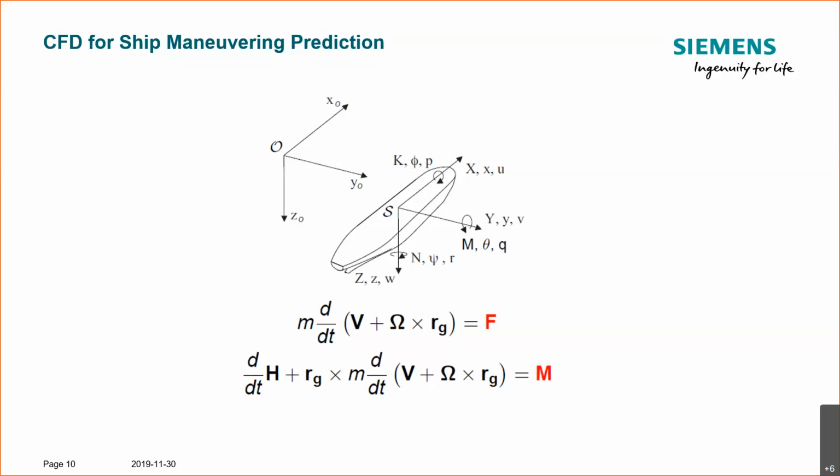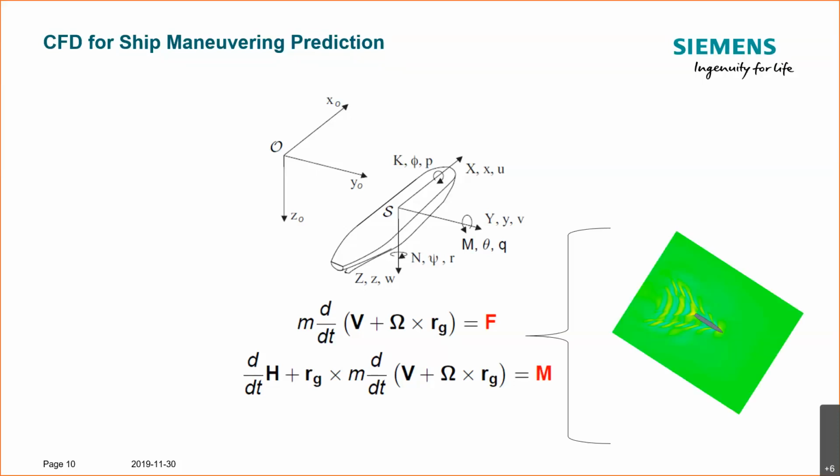So let's make our lives easy and just resort to Navier-Stokes. So basically, we will build a CFD model of the ship in a finite domain and specify rudder and propeller action, and then we'll get the motion responses and all the other sought after metrics from CFD. Very convenient. Unfortunately, we don't always have the resources and the time to do such an analysis, and sometimes it is not required to go into fidelity levels at the highest level.